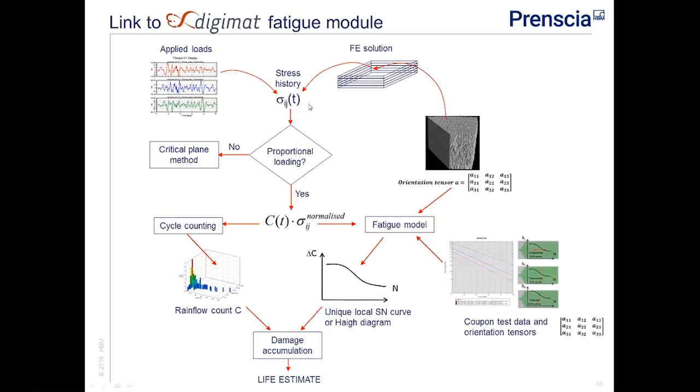It takes advantage of our ability to use the multi-axial assessment at each calculation point to partition the stress history into a scalar multiplied by a normalized stress tensor.